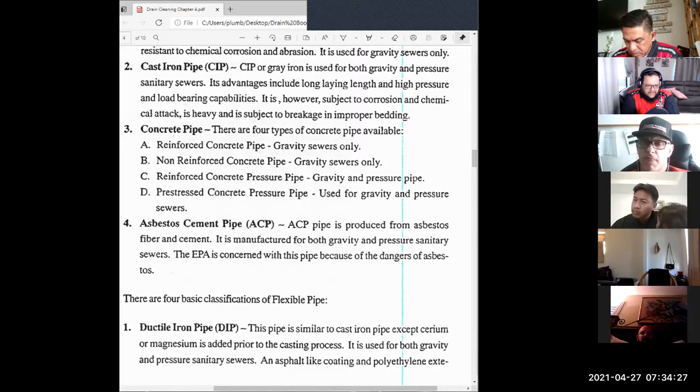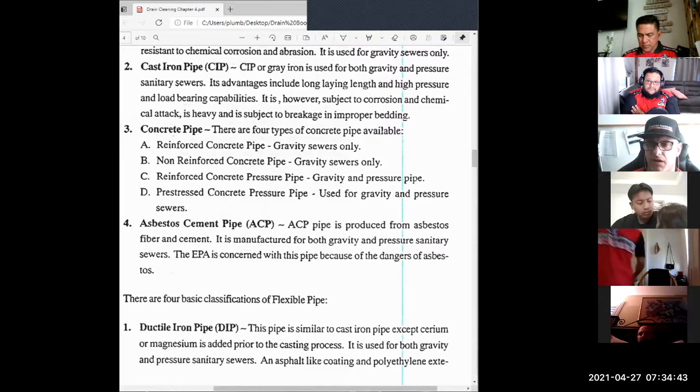You had something to say, Ken? Yeah, so supposedly when you confront an asbestos pipe, you're actually not supposed to touch it. You really shouldn't be messing with it. But there are times where we as plumbers have to make repairs regardless. Safety should always be first, and there are proper ways of handling it. If you hire somebody to properly handle it, as Josh said, water is actually your best friend, because it's the fiber and the dust that is the problem. And of course, a respirator.